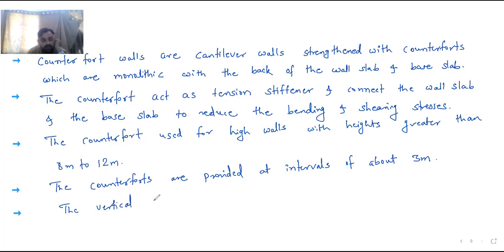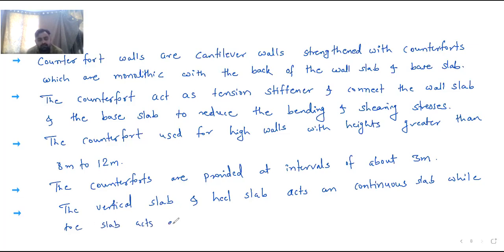The vertical slab and heel slab act as a continuous slab, while the toe slab acts as a cantilever slab.